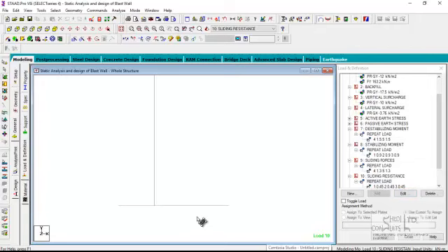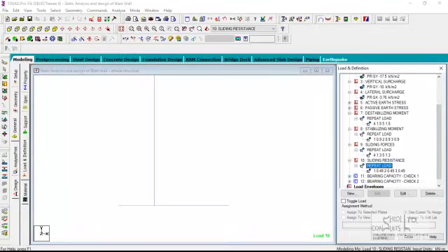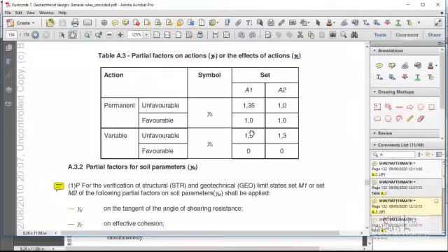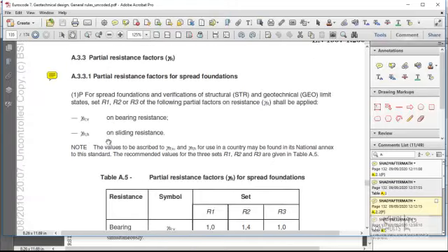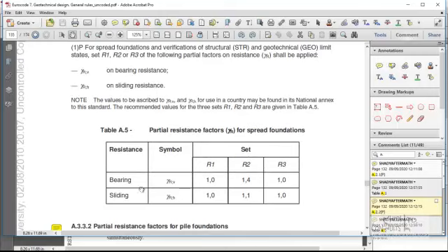Those are the loads that are resisting the sliding, because when the forces are causing sliding, the sliding resistance is a function of the coefficient of friction between the foundation base and the soil. That coefficient of friction times the normal reaction. So the code now states that the factor of safety against sliding resistance, for the set of combination factors we specified, is 1.